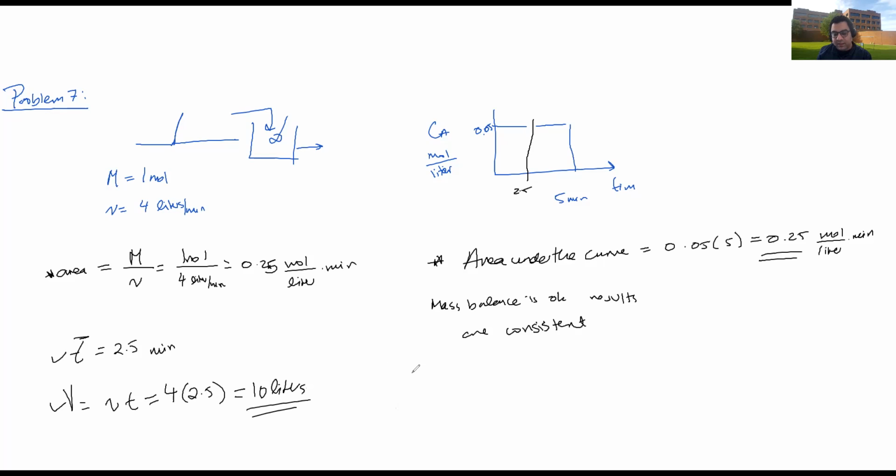So this is how you get these types of parameters. And then in order to get E, the experimental curve, all you need to do is use this equation. We haven't presented this equation in the slides. You won't be tested on it, but it's good to know it. E is equal to C over M divided by V, right? And this is how you get the relationship between your experimental curve and your concentration curve. M over V is 1 over 4, as we said. So C over 1 over 4 will be 4C. So the value for E is equal to 4 times the value for C.